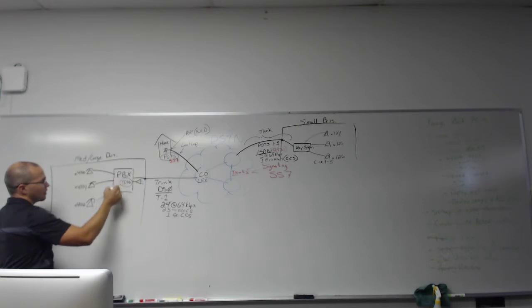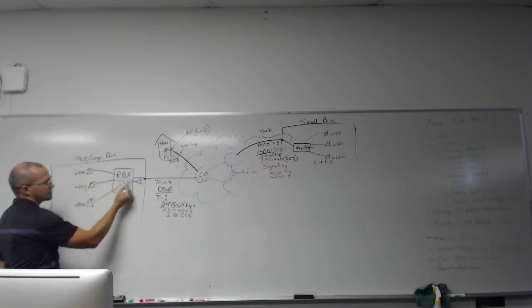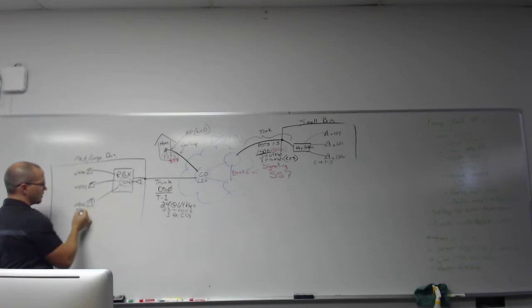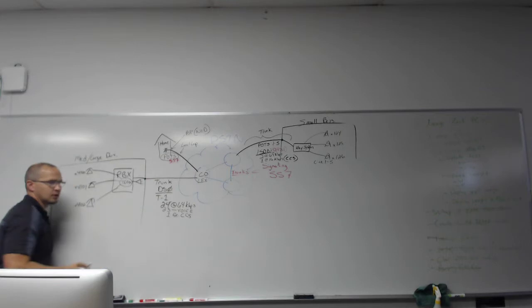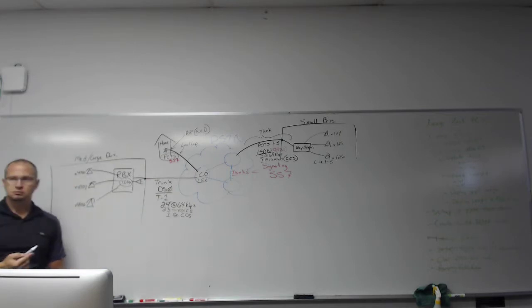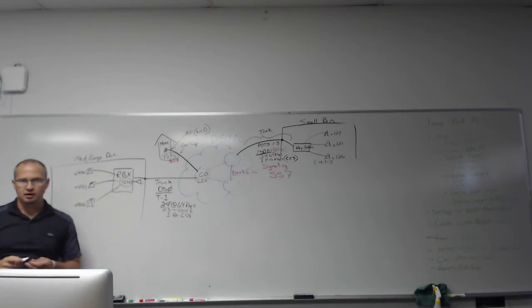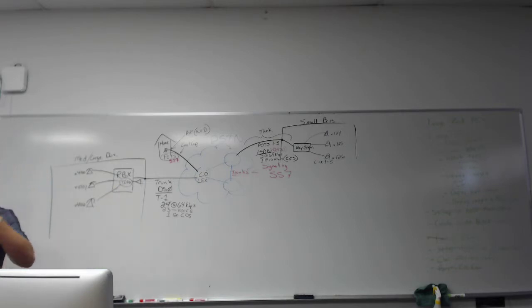It's allowing all of these connections, and it's using time division multiplexing to allow a connection to be made when this phone call wants to be made. When this phone seizes a line, dials 9, it's going to grab one of these 23 channels to communicate out to the internet. So time division multiplexing allows one-to-many or many-to-one communications.